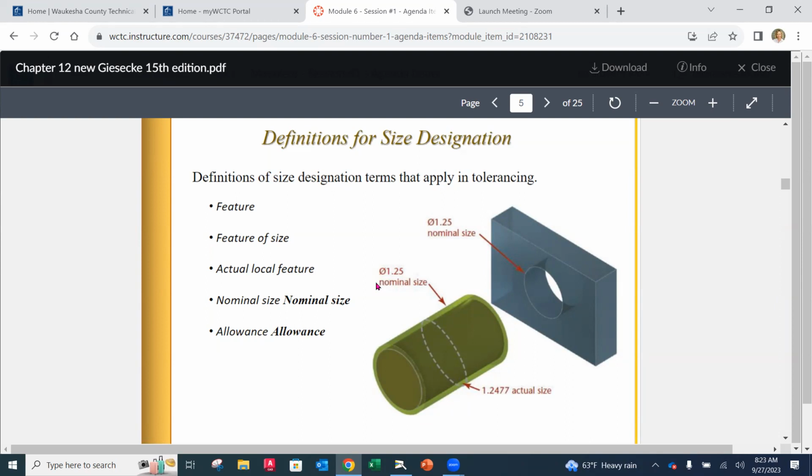I do have a drill chart for you that is standard, so that you can see what is standard. When you're putting sizes of holes on, you want to be at a nominal size. Same thing for metric, and those are usually to about the millimeter increment, because they have drill sizes that correspond to those. So nominal size is going to be that nice number that relates to something, especially in the system of measurement that you're looking at.